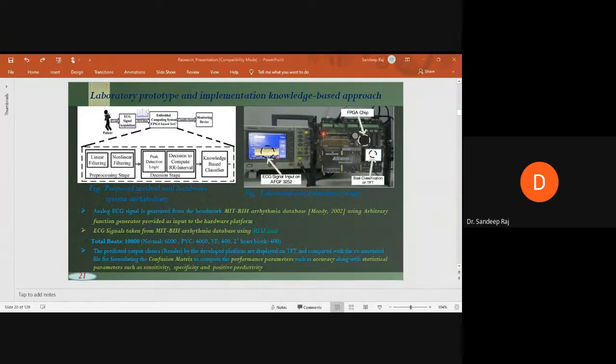What our contribution to this algorithm is: first, we have implemented this PCA algorithm in hardware, on an ARM-based microcontroller platform. And secondly, we have modified the PCA algorithm and chosen the cyclic Jacobi technique, due to its simplicity and accuracy, to compute the eigenvectors of a symmetric matrix with faster convergence. So we have combined the standard PCA method with this cyclic Jacobi method, and the components calculated as the output of the PCA are uncorrelated and orthogonal to each other.